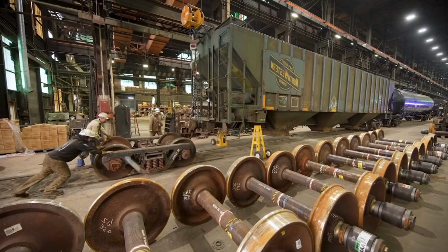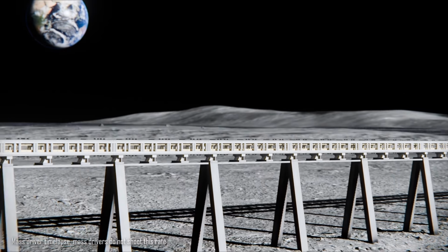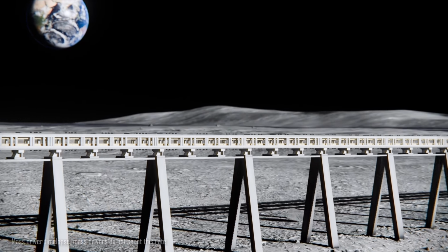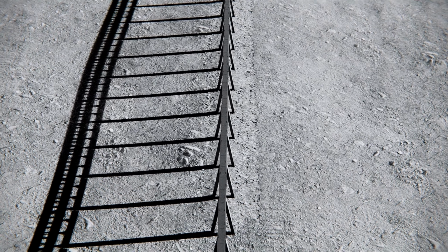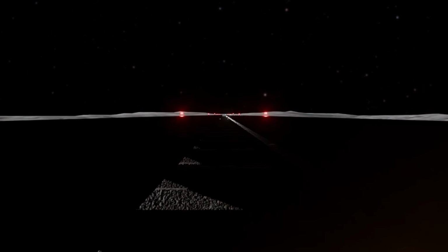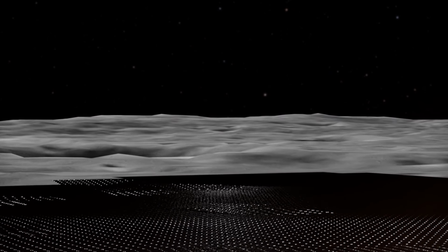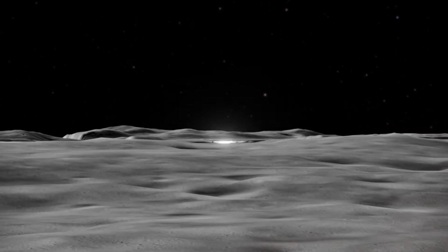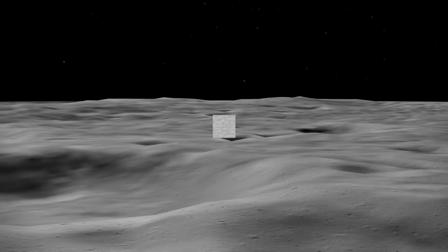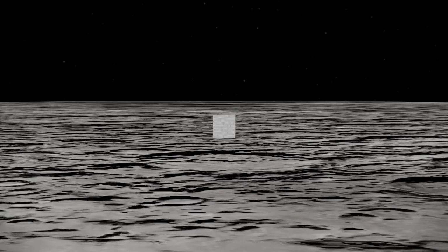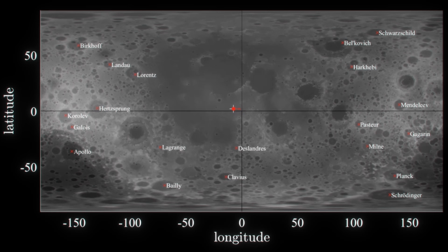Except here it is not spread across a rail car and 8 wheels. It is acting as a moving vertical load through every coil section of a precision launcher that still has to remain aligned over kilometers. So the practical answer to elevation is none. Just treat the mass driver as a horizontal piece of infrastructure, and fortunately the moon curves away about 3.7 times faster than Earth does, so we only need about 60 kilometers of cleared line of sight after the muzzle for the payload to be 1 kilometer above the lunar surface.